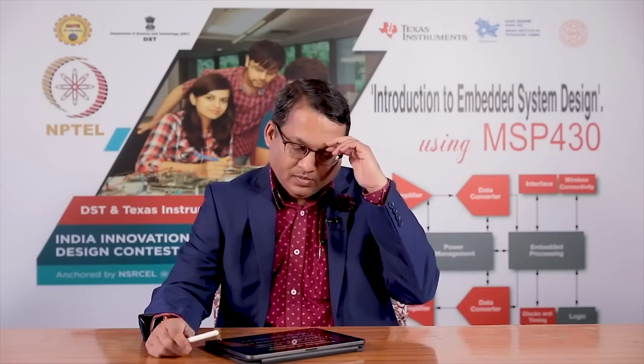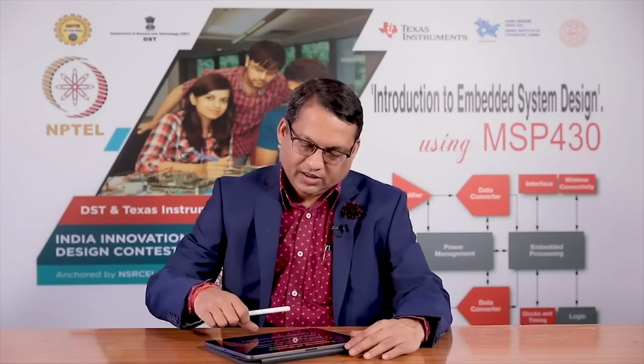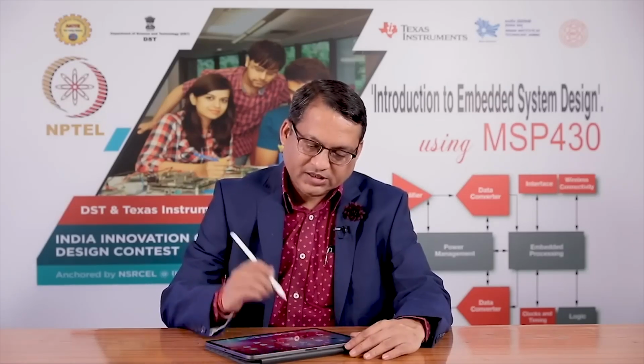Okay, so we have seen how the pins on a microcontroller are programmable, and you can program them to be of input or output types. Now, let us see the next point, and it says that if you define a pin to be of output type, then it has a capability to provide about 30 to 40 milliamperes of source or sink current. Now, what is the meaning of source and sink current? Let us look at a sketch.